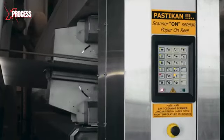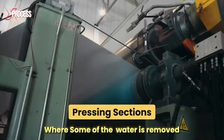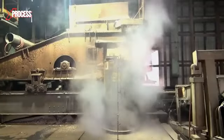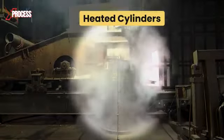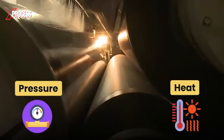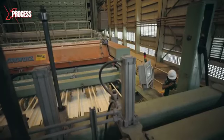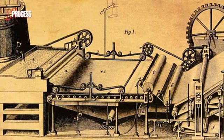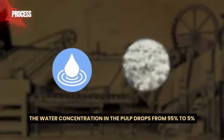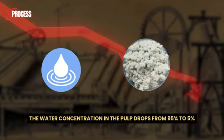After the initial formation, the paper sheet passes through pressing sections where some of the water is removed. Next, the sheet passes through heated cylinders that apply pressure and heat to complete the drying process. This process reduces the water content and provides strength to the sheet. Between the input and output, the water concentration in the pulp drops from 95% to 5%.